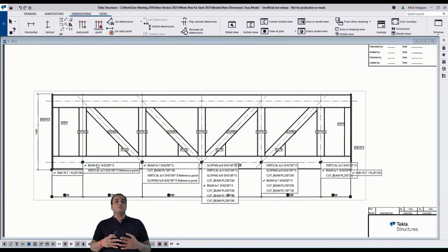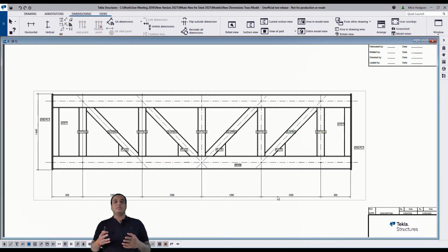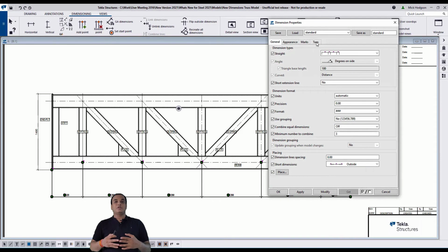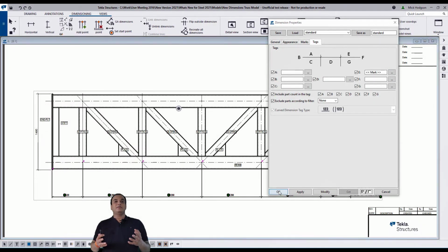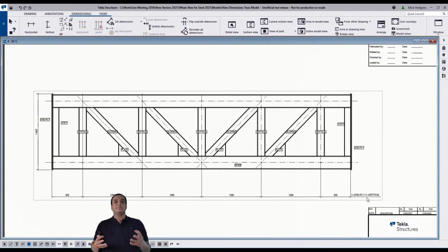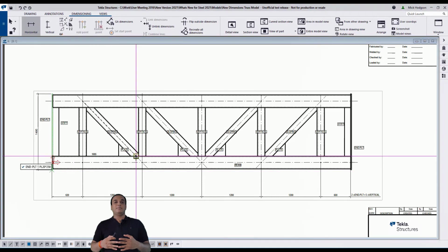And after creating this, I will turn on the associative part, and easily I can change it from one part to another part. So let me change all the associative points to the vertical members, and this also works for tagging. So we can tag the part name, for example, and I just have tagged the part name, which is visible here as a vertical member.